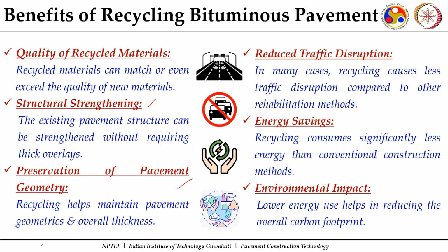The best part is that we are removing the existing distressed layer, which is not adding anything to our structural strength, and then we put up a new layer over it. Some of these recycling processes, as I mentioned, are done in place and take less time, so the traffic disruption is even less compared to standard rehabilitation processes. There are also energy savings, because you are reducing the dependence on virgin aggregates and neat binder.